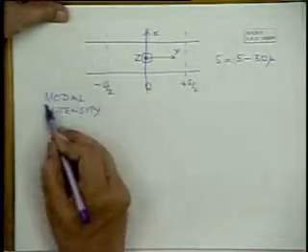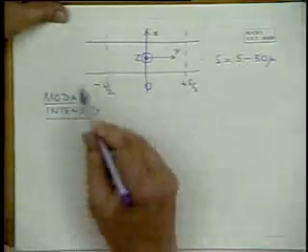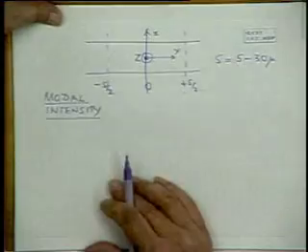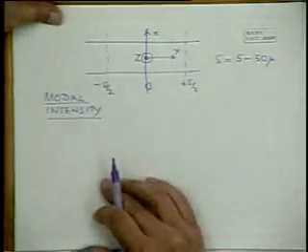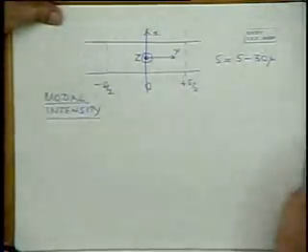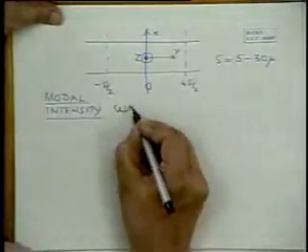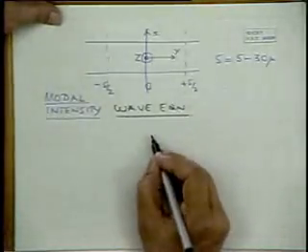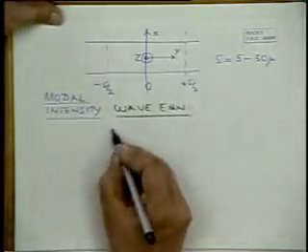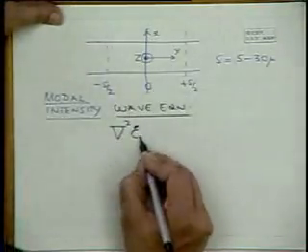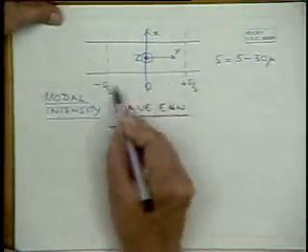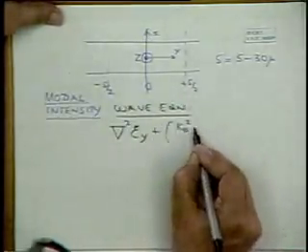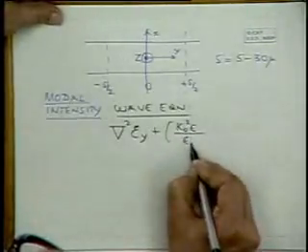So obviously, again, we are interested in looking at the electromagnetic fields in this configuration and the way the electromagnetic wave propagates. And so we have to look at the wave equation, looking at the electric field distribution in this direction: del squared Ey plus k0 squared epsilon by epsilon 0 Ey is equal to 0.